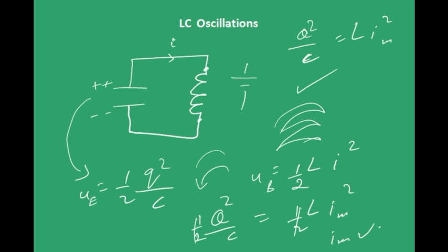And energy gets transferred, right? Let us see how it gets transferred. Let us observe it in detail. First of all, what happens? There were positive charges here and negative charges here. And say initially there is some current, not the maximum possible one. Slowly, because of this current, magnetic field lines are set inside this inductor and charges are reduced, right?